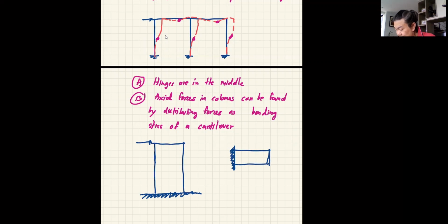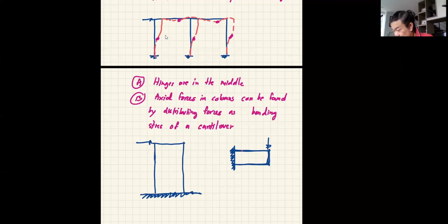Because generally, the buildings, when it comes up against the earthquake or the wind, it's basically a cantilever beam. So when you try to look at the stress, you know this is tension and that is compression. Correct? And somewhere along the line, there is this. What is that? Neutral axis.